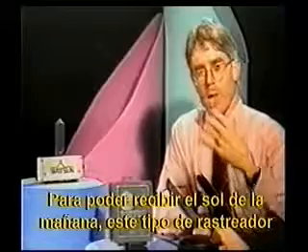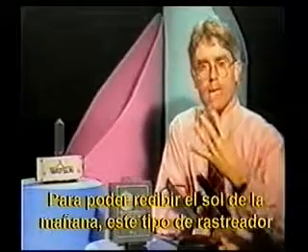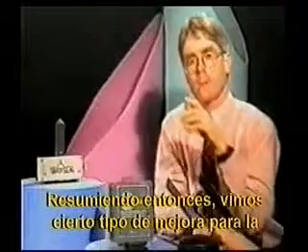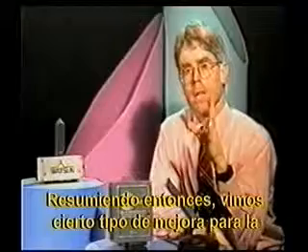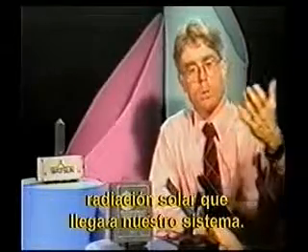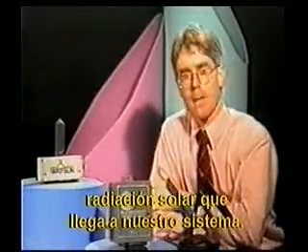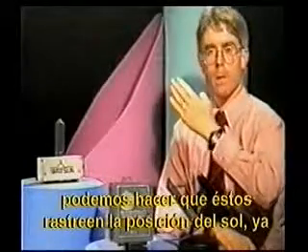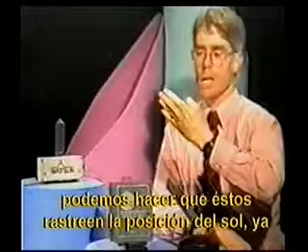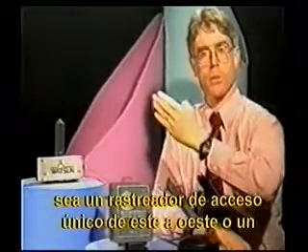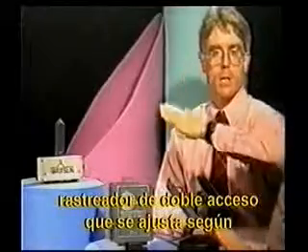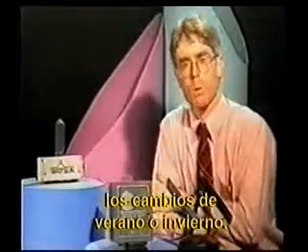This type of tracker has to wait for a morning reset from the morning sun in order to find the sun in the morning. By way of summary then, we've looked at a certain type of enhancement to solar radiation coming into our system. Instead of having our modules just mounted at a fixed angle, we can have the modules track the position of the sun, either a single axis tracker moving east to west, or a double axis tracker that adjusts for summer and winter changes as well.